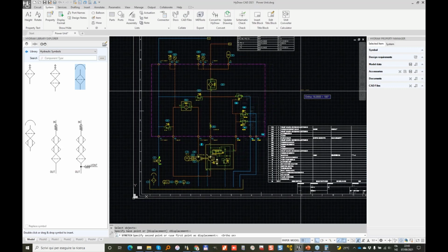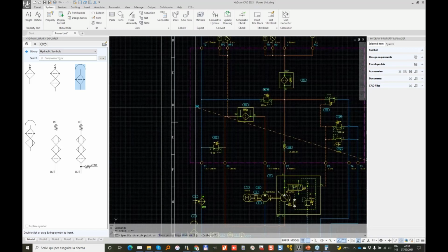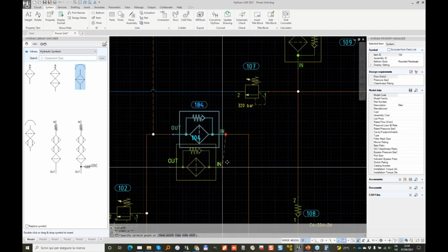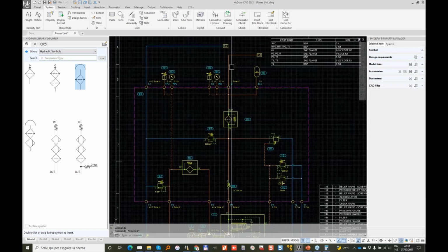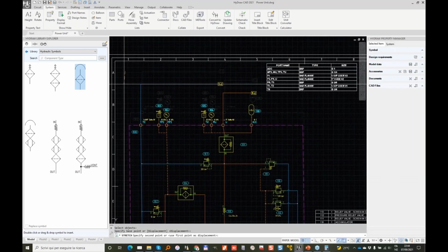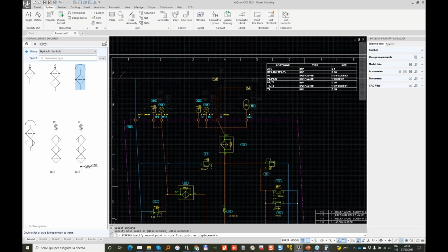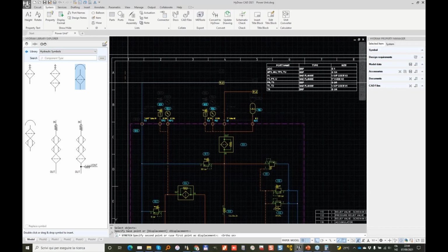Balloon for the envelope, we put it somewhere on the top left. That's the envelope. We also can reduce a bit the space inside the manifold for better readability using the same AutoCAD commands. Stretch. If you struggle with the ortho on, press F8. So then it will be only horizontal or vertical. F8 again will remove the ortho mode.